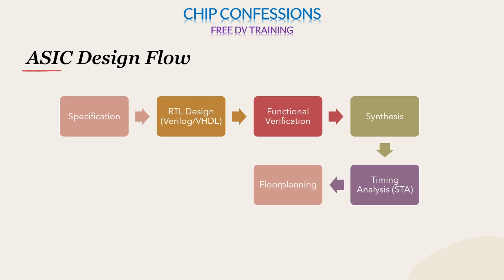Later on, once this timing analysis is checked, we go for floor planning. Here, as I said before, we will be having blocks like combinational blocks, sequential blocks, memory blocks, IO blocks, or any logical computational blocks. Those blocks we will be having, and in floor planning we will see where those blocks could go and sit. That we will check at the floor planning level.